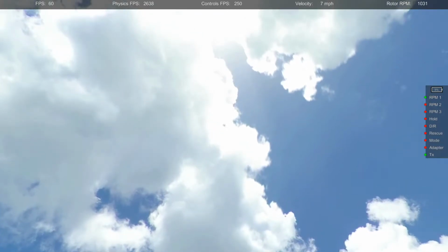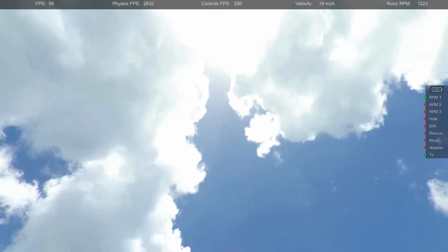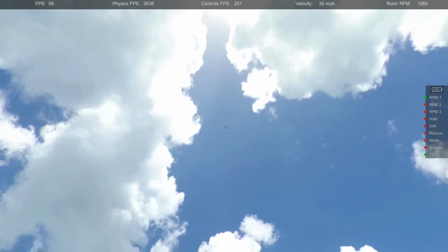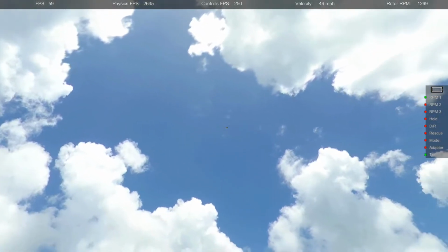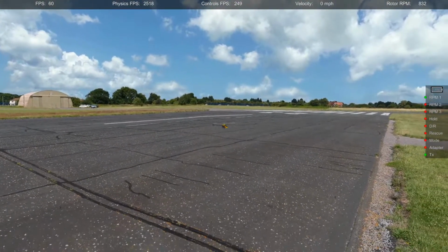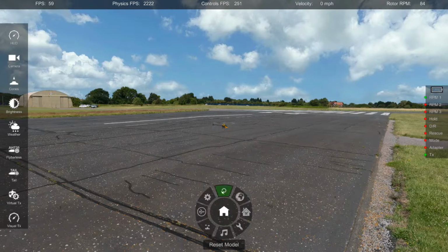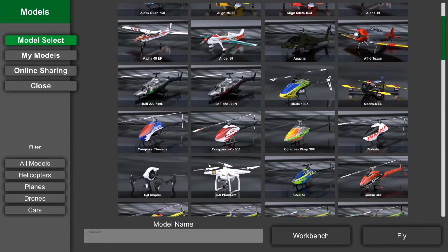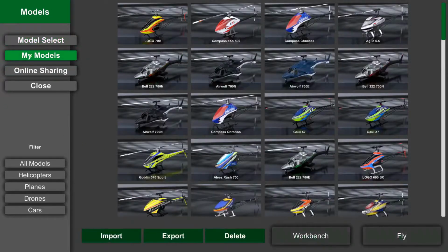Now, it's got a bigger wingspan. This is the thing you have to remember. If you have a span constraint, you want the other solution, that elliptical solution. If you don't have a span constraint, if span can be unlimited, then you want this new solution. And this is the part that we all miss. And I can tell you exactly how many airplanes have used that new curve C. The number is 8. And all 8 of them have been constructed in one particular place. That's not quite true. There's two places you'd have to go to in order to see both places where all these airplanes have been built.